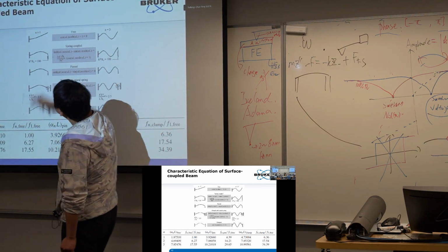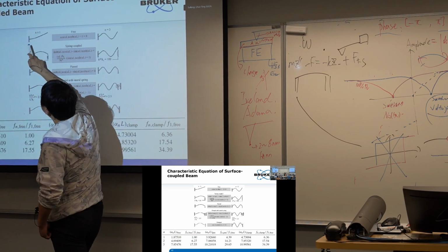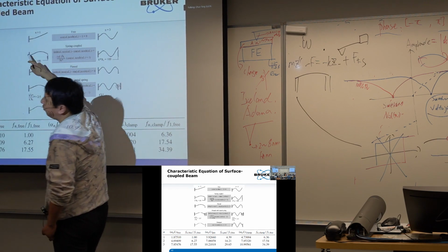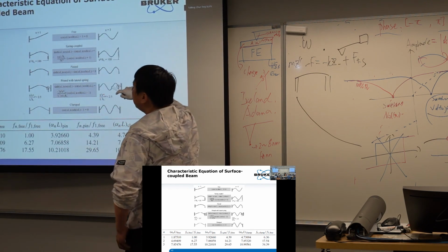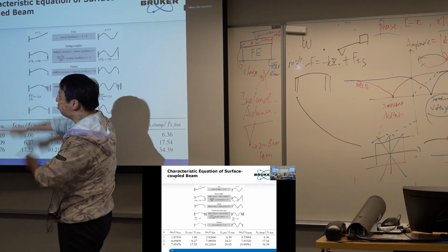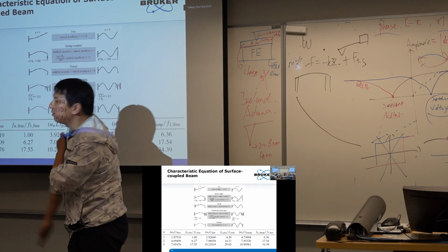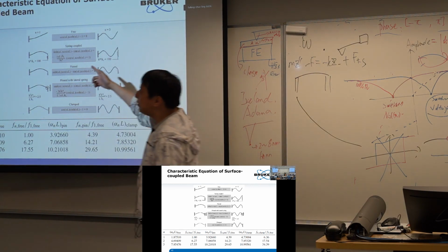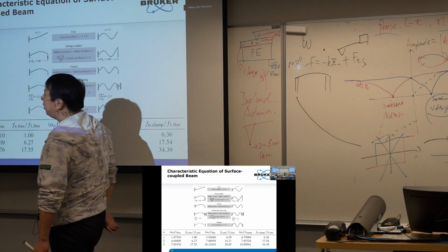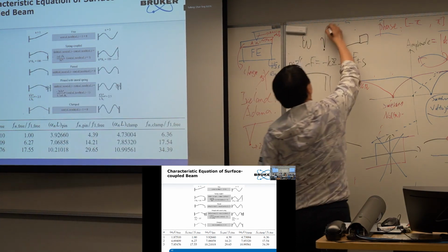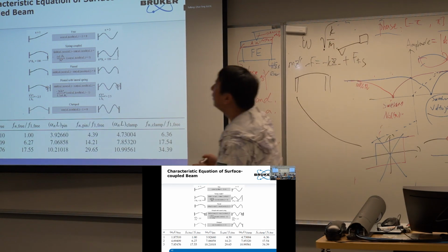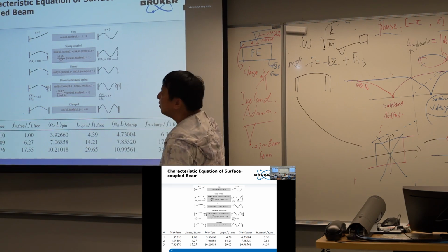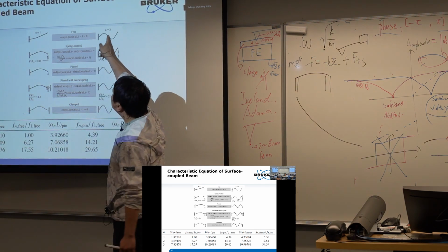For example, n equals 1, and on this beam, one side is fixed, one side is free. That's our AFM cantilever. So n equals 1 means the probe moves like this, which is the vibration we described yesterday, and its resonance frequency we got yesterday, the square root of K over M. Then this cantilever can also move in other ways, for example, like this.